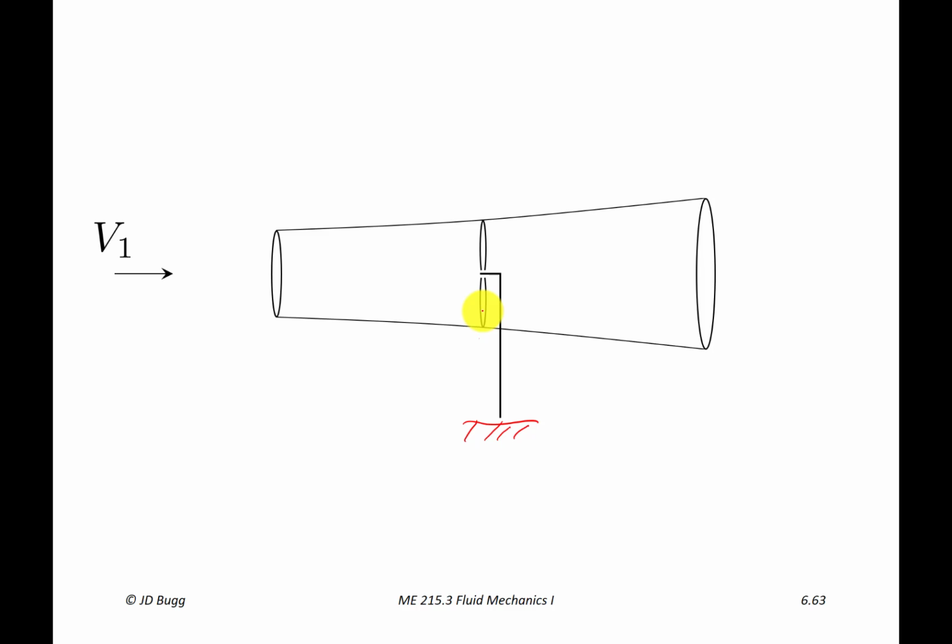Now, as the air approaches the rotor plane, it's seeing this as an obstruction essentially, so it's slowing down. And we're going to study how much it slows down in quite a bit of detail here soon. So that means that the cross-sectional area of this stream tube has to be smaller here than it is here.